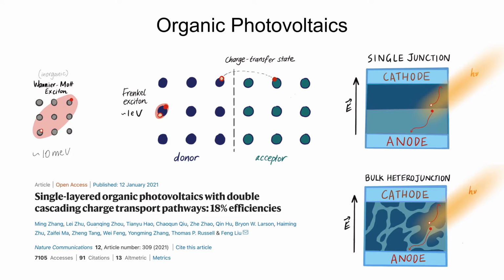Unlike their inorganic metal counterparts, intramolecular forces play a dominant role, and the excitons formed in organic solids or polymers are much more tightly bound. This meant that charges can only be separated when they're at the interface of materials of different work functions. However, only about 10 nanometers of material closest to the interface can contribute to the photocurrent generation.